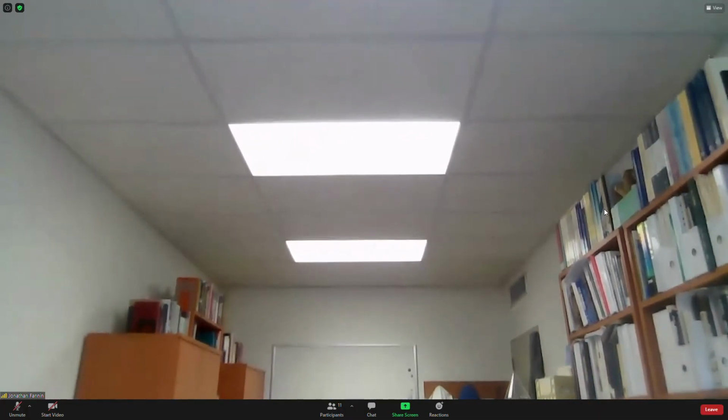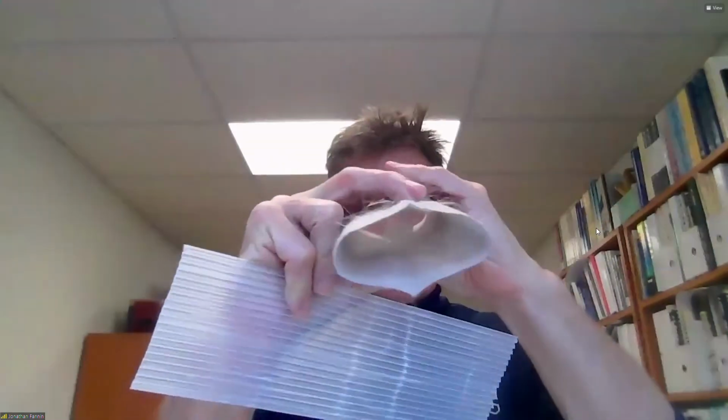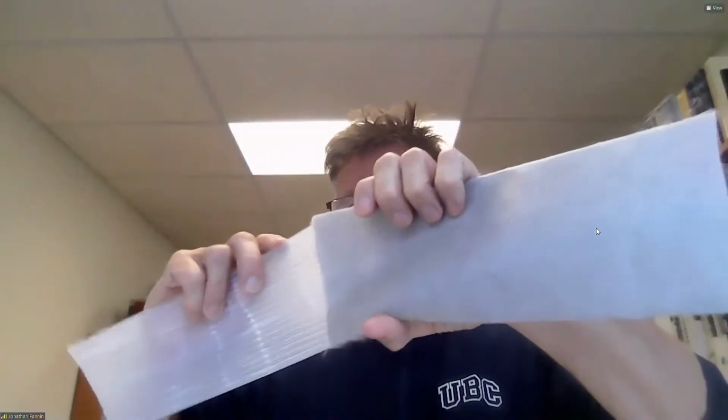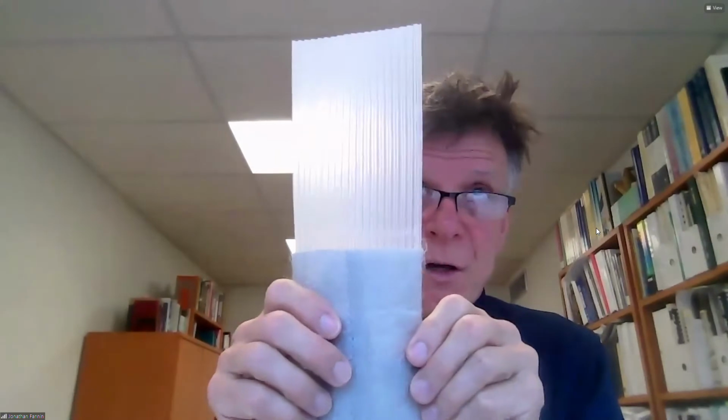If you're going to use wick drains, they're well established, and in fact, the current version of wick drains, once again, there's the drain, and then we have the filter sleeve, if you like. So drain going into filter sleeve. This is really simply, I'll call it a polymeric, a geosynthetic version of what was used prior to the advent of the polymeric wick drains.